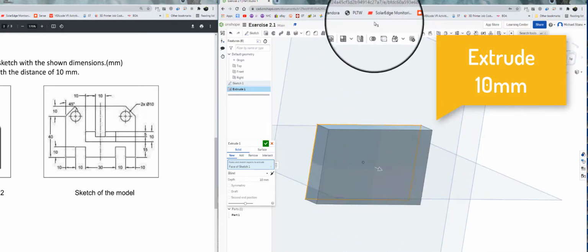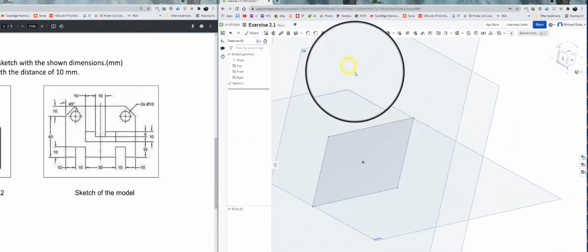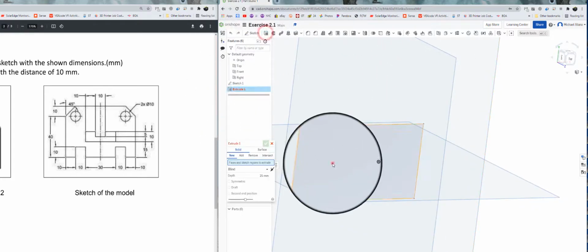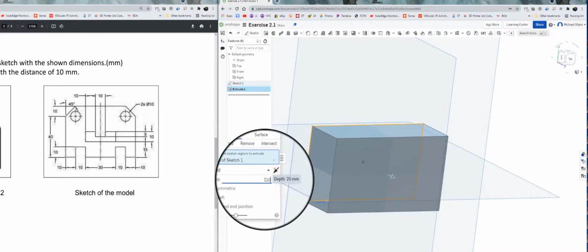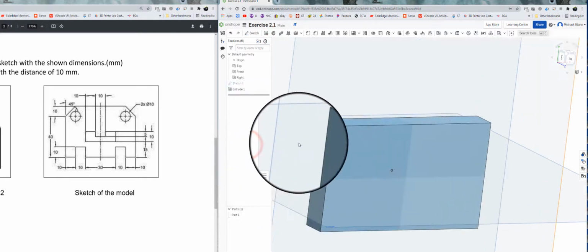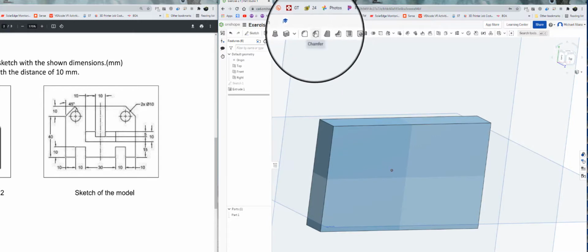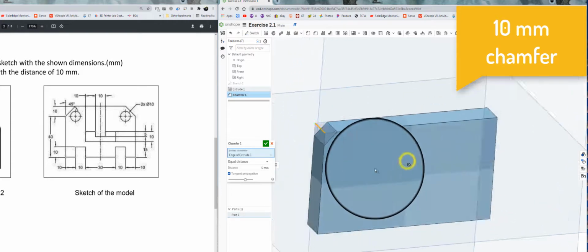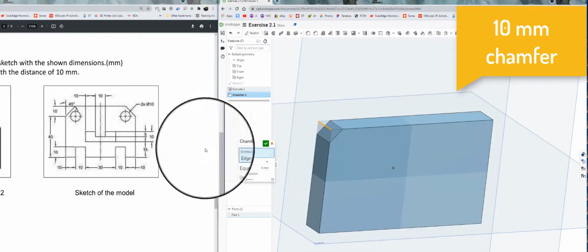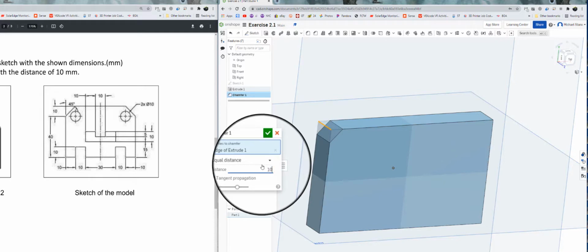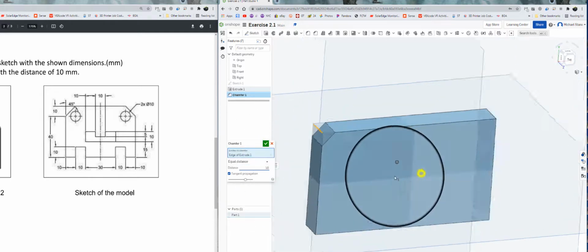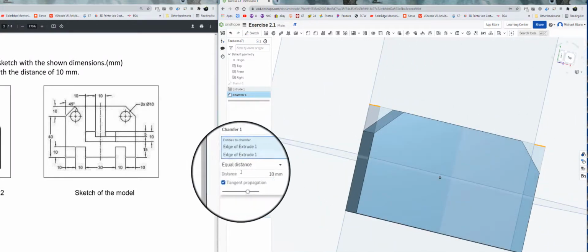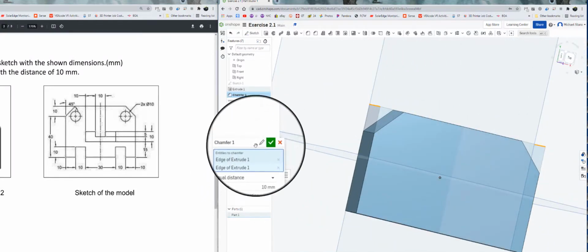I'll add a chamfer on these corners. Okay, add the chamfer. So click the chamfer tool up here. Click that. Okay, and it's distance of 5. We need 10. And there's the chamfers right there. Edge to edge, equidistance, as we got. Good.